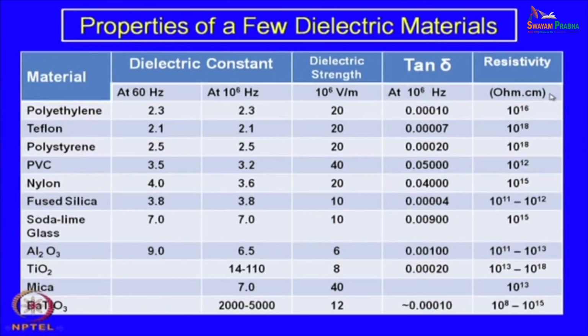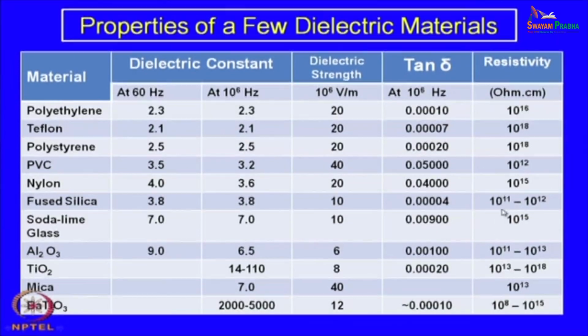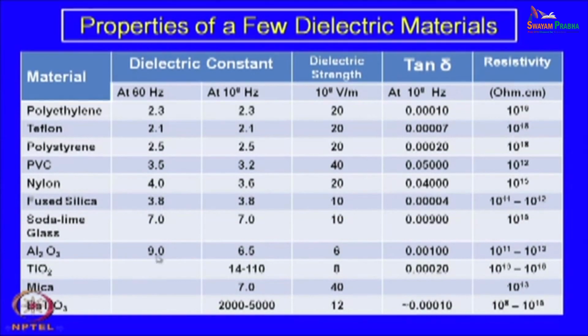Resistivity is obvious, all of them have very high resistance, but it varies to some extent, but most of them tend to be higher than 10 to the power 10 ohm centimeter. So, these are in fact important dielectric materials used in industry for different purposes.